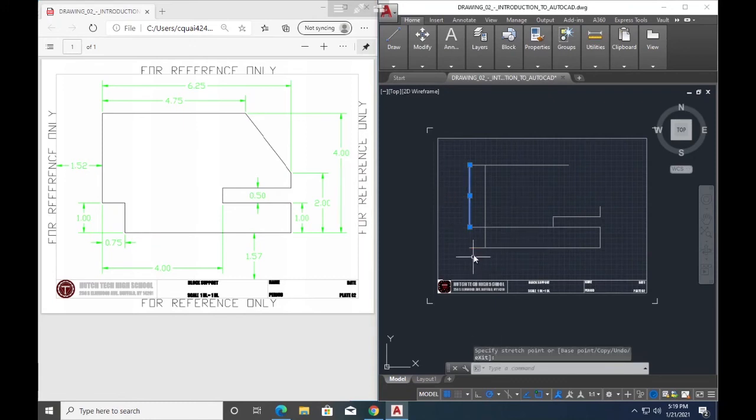All right. Now I'm going to do the same thing over here. I'm going to select on this line. I'm going to take this node right here, this left node, and slide it over until it touches where I can get this green square again. Doing the exact same thing as the trim command, but this time I didn't have to go into any other commands. I was able to manipulate and modify the line the way I wanted to.